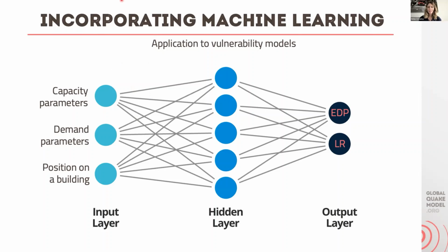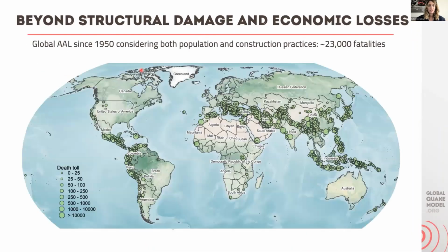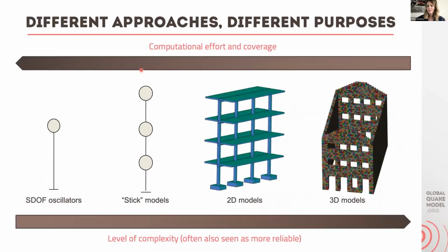So we do have a question on the Q&A, and one of the participants has also answered it, thank you, but let's hear your take on it as well. So the question is, a simpler surrogate model which has a capacity curve fitted to the curve of the original more detailed multi-degree of freedom model, will it behave similarly in the time history analysis? So I think this obviously depends on whether you are looking at low-rise buildings or high-rise buildings with many degrees of freedom and so on. So is this something that you're looking at as well in terms of validating or calibrating your simpler models to make sure that they do have similar response to the multi-degree of freedom?